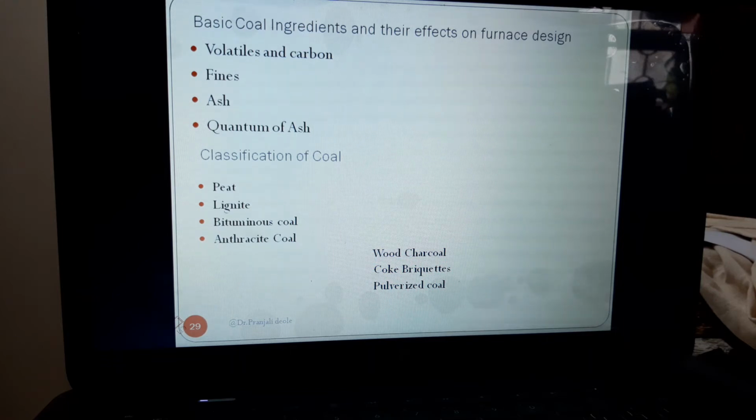The higher the ash content, the slower the coal burns compared with low ash content coal under identical conditions of feed rate and excess air supplied. Therefore, a given ash content coal can burn at different rates depending on how fast and how effectively it is surrounded by air. This phenomenon can be observed by more intensified glow of the coal burning.